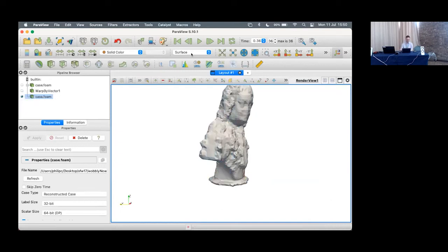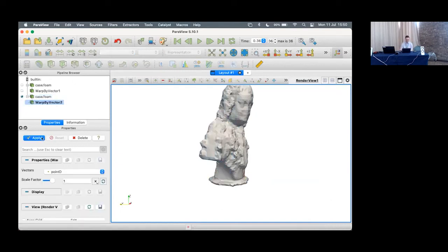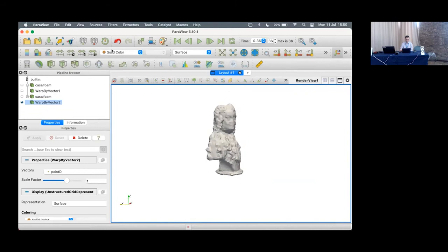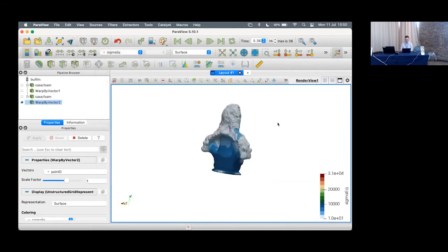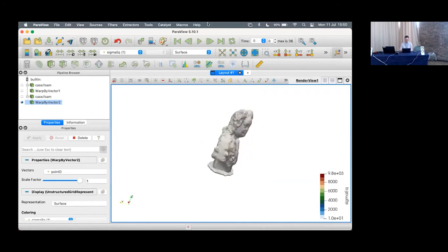If I look at that case in comparison, the stress can't go above whatever the maximum is. So in this case, this is elastoplastic. When he bends back the first time, it permanently deforms. So it dissipates energy. Then whatever remaining elastic energy there is, it'll just bounce around that point.